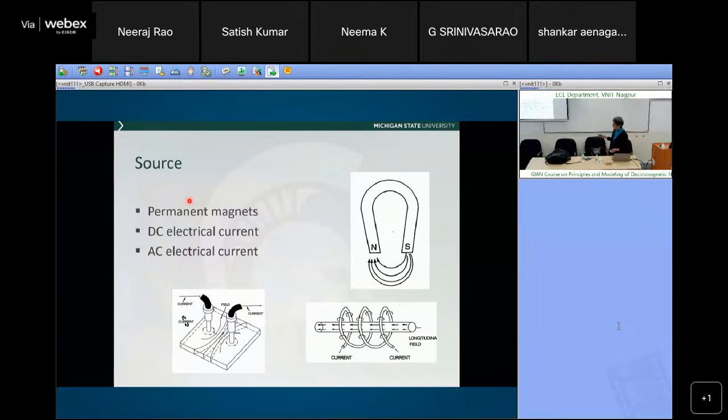I'll talk about that also in the pipeline. If you magnetize it in this direction, then your current has to be encircling, a coil encircling. In which case you don't really need contact, but the magnetization itself is one time. It is set up and that's it, and then you're scanning for leakage field. So that is what determines if it's a contact method or not.